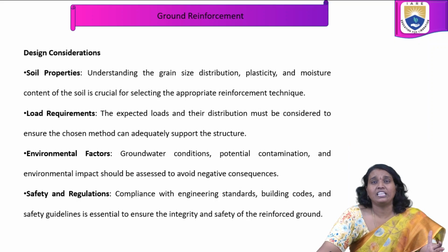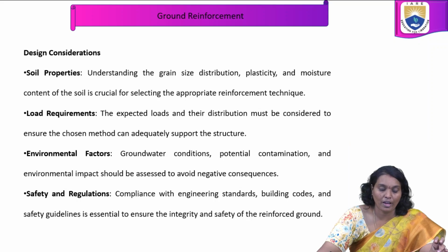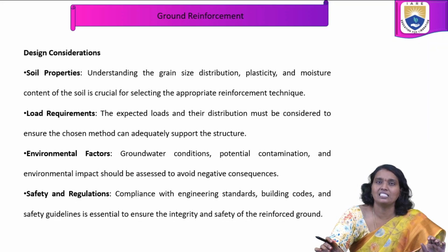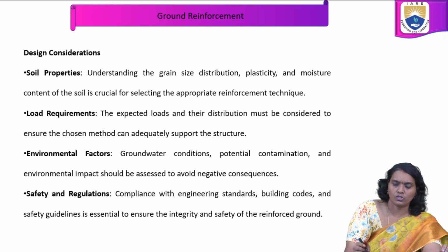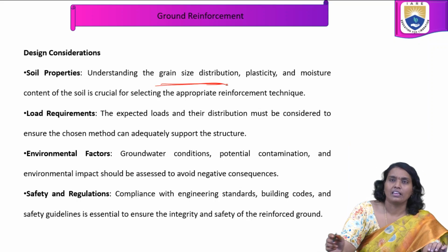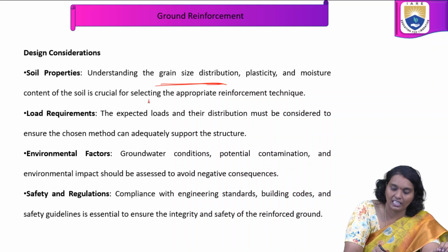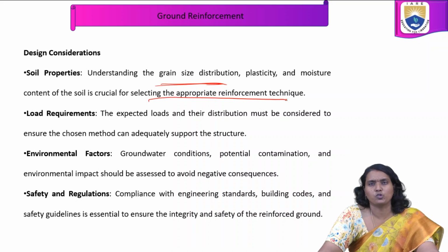These are some of the design considerations: soil properties, load requirements, environmental factors, safety and regulations. In soil properties, understanding the grain size distribution, and also the plasticity and moisture content of the soil, is crucial for selecting the appropriate reinforcement technique.